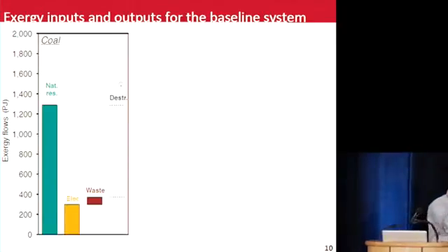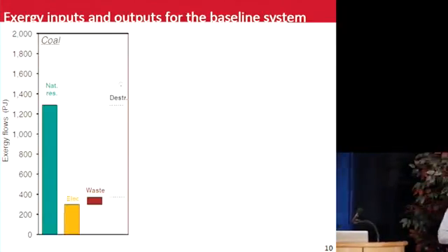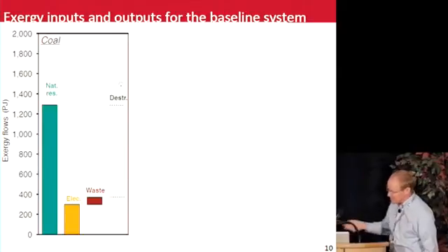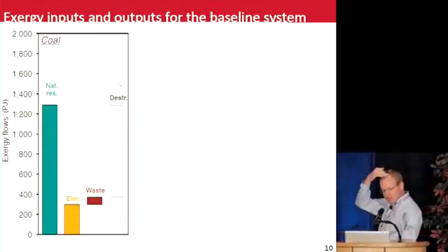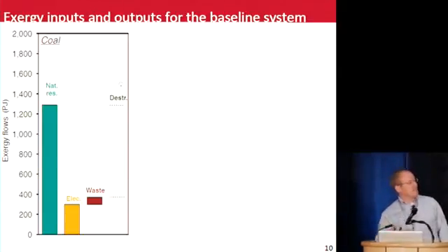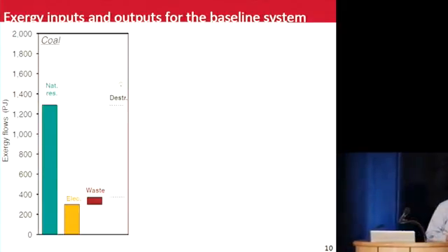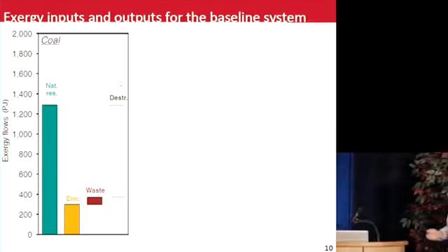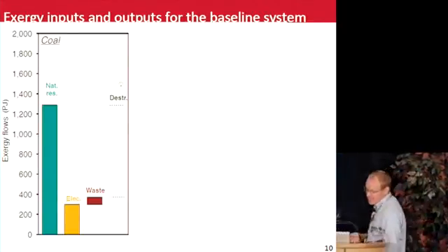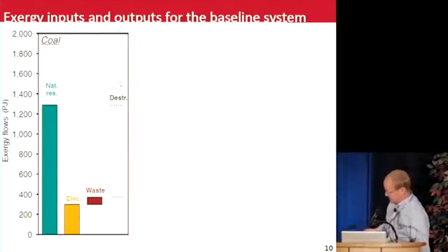This exergy is then partitioned into three categories. Output electricity that we care about, that's the yellow bar, the final product. The exergy content of waste flows, the things it's putting out in the environment. And then a very large term of exergy destruction. Again, this is not an ideal or reversible process, so there is exergy destruction involved.